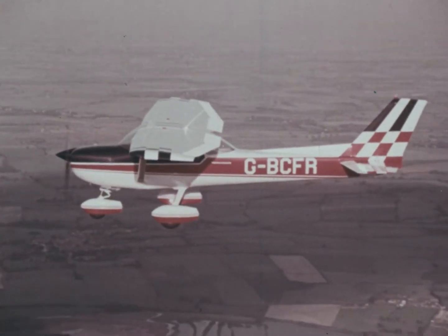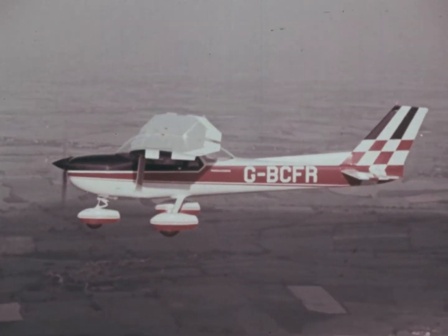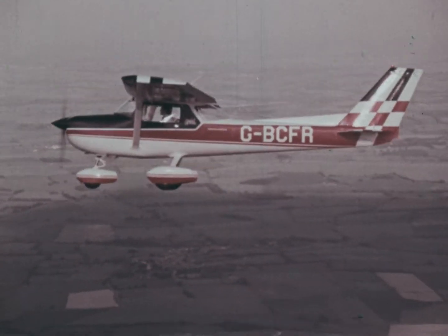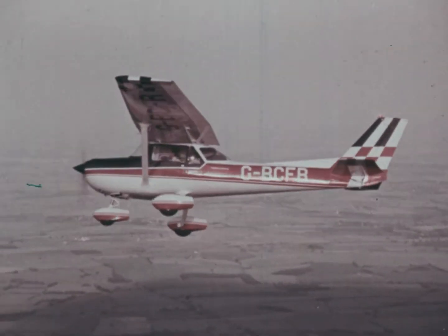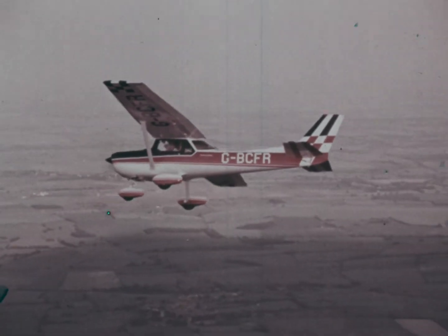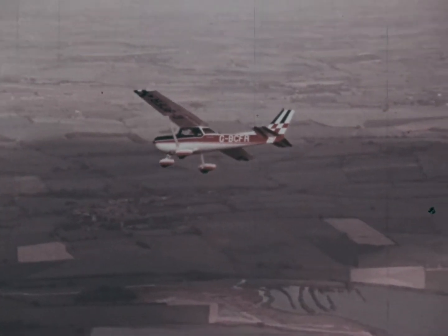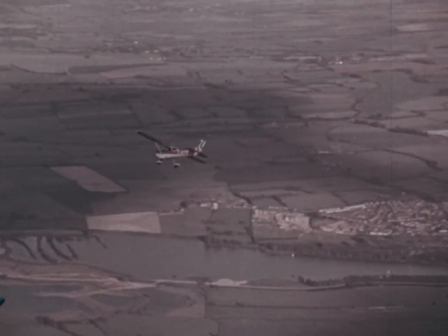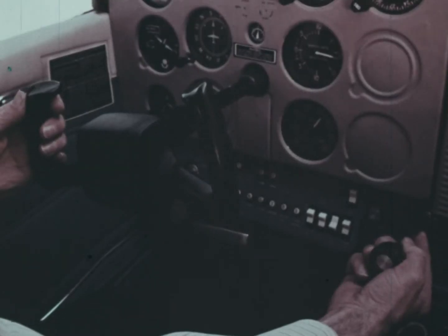No airplane is fully stable laterally, and if an involuntary roll of more than a few degrees is left uncorrected, the lift from that powerful wing acting at an angle to the airplane's path will pull it into an unstable descending turn. To recover from it, we must use the controls.